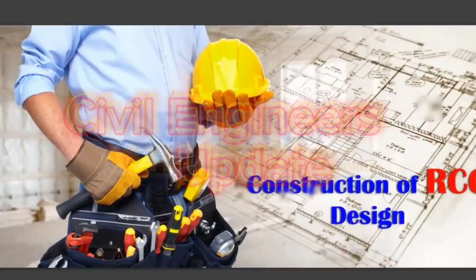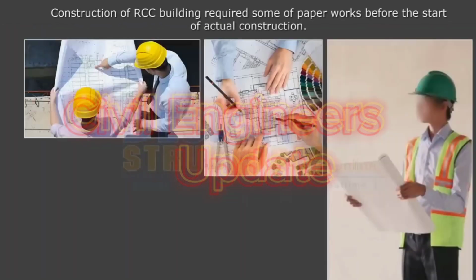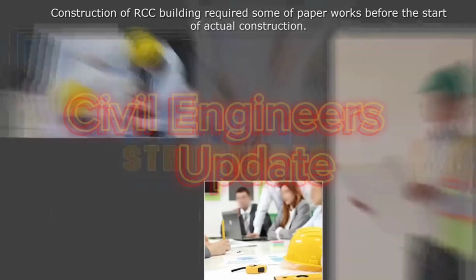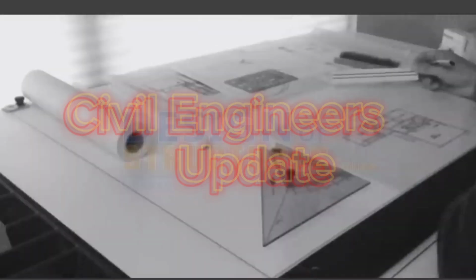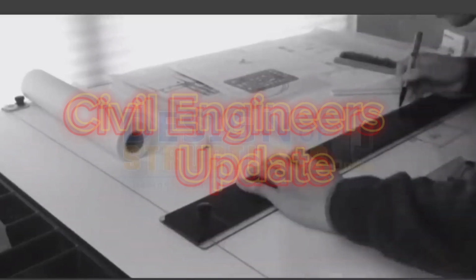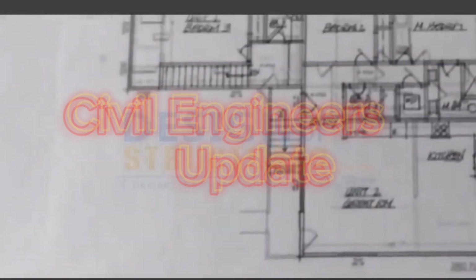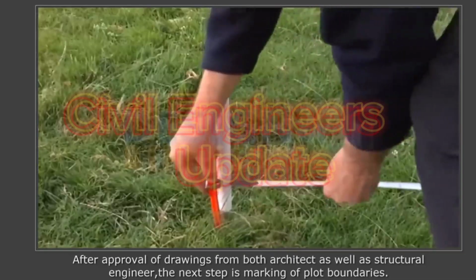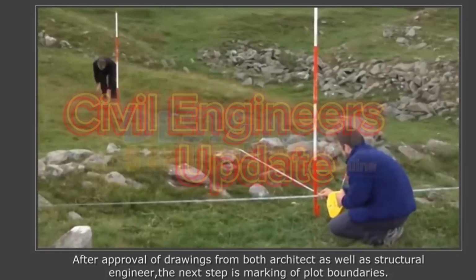Construction of RCC design. Construction of an RCC building requires some paperwork before the start of actual construction. The very first stage is preparation of drawings as per requirements of the client. Once drawings are completed, approval of drawings is important. After approval of drawings from both the architect as well as the structural engineer, the next step is marking of plot boundaries.